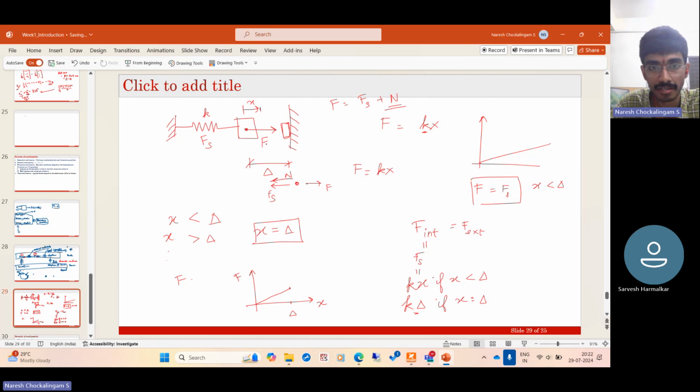And if the total force is F, the normal force is just F minus Fs, right? So you can have as high a normal force as you want. This is rigid, so it can take any amount of force. As you increase the force, the displacement will remain constant. So the force displacement response will be like this. Force can even go to infinity. So this is a kinematic nonlinearity.